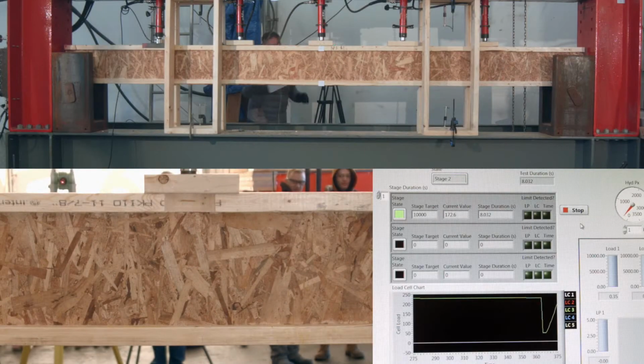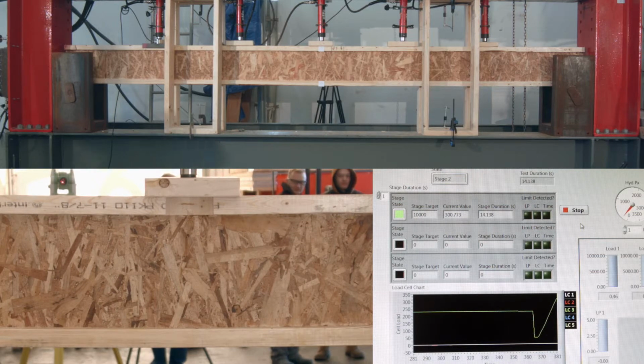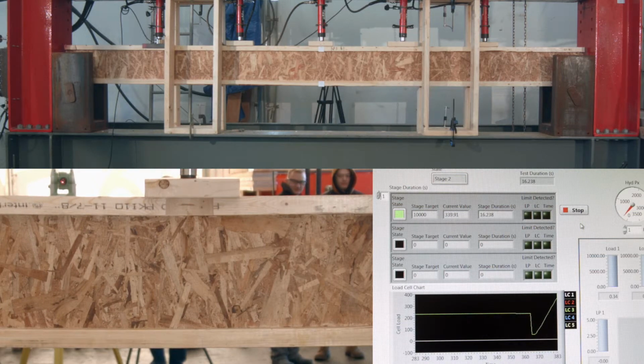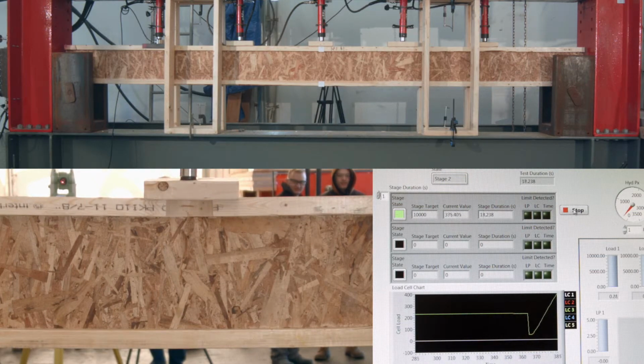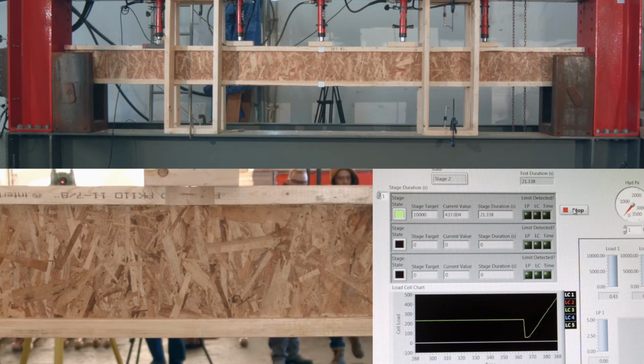A common mistake in the field is to nick the upper flange when drilling holes for utilities through the floor. Nicking the flange has an adverse effect, as it severely weakens the lateral stability of the flange. You can see the flange sticking out, even with the bracing in place.